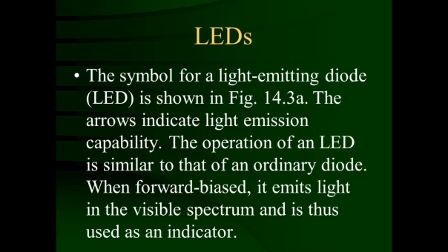How does it emit the light? What is happening actually inside? In a semiconductor material, different types of impurities, arsenic, gallium, phosphorus, etc., are utilized in different proportions. Because of this, the electrons go from the ground state to the excited state, and again when they release the energy in the form of photons, hc upon lambda, they come back to the ground state.